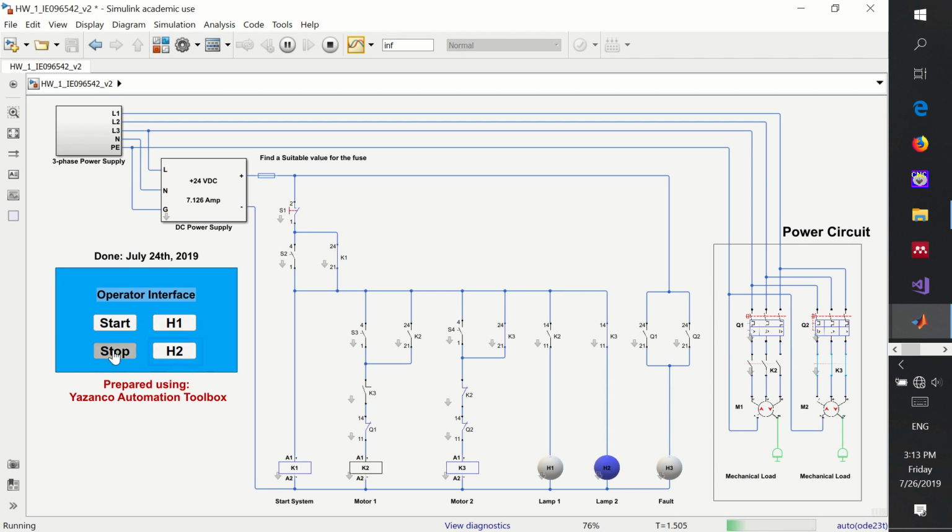And now whenever we are starting the first motor, we need to stop the circuit, start it another time, and now we need to start the push button to test the response. You can see here now we try to start it, but due to the overload condition, now the first overload actually tripped, and here we have a fault indication appearing on the operator console or operator interface.